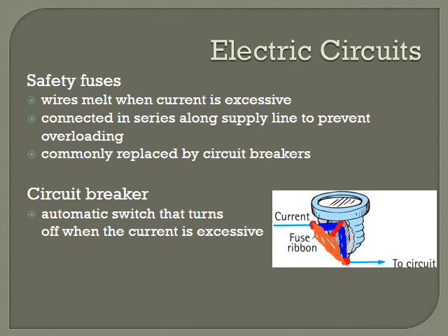And so now you've got a penny that's going to make the connection for you, but unlike a little fuse ribbon, which will heat up and melt when you run too much current through it, a penny, you can run a lot of current through it. And so therefore that essentially gets rid of the entire point of having a safety device, that you might as well just have a plain old wire running through there. So fuses were unreliable because people didn't keep a good stock of fuses on hand, and they would start putting pennies in and you would get house fires.